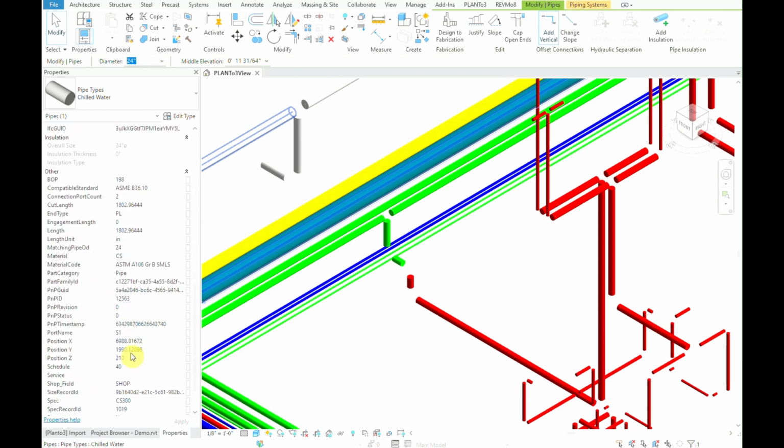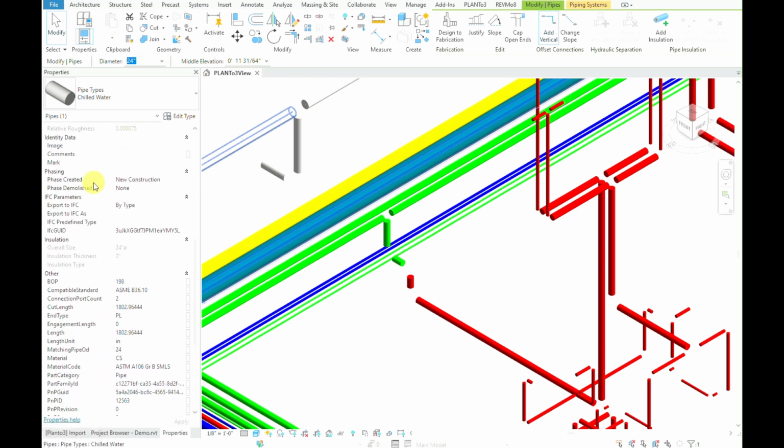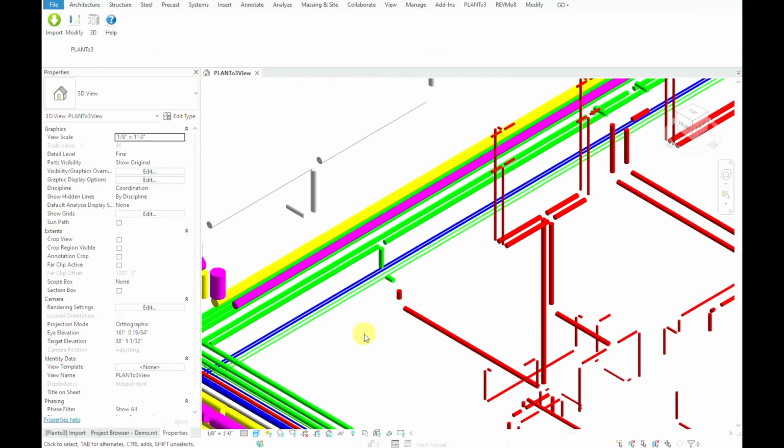If one or more entities need not to be mapped, you can always use Create Geometry option to create a REVIT generic model instead. As will be shown later, you can also create a REVIT family type using an AutoCAD PLANT3D imported entity geometry.